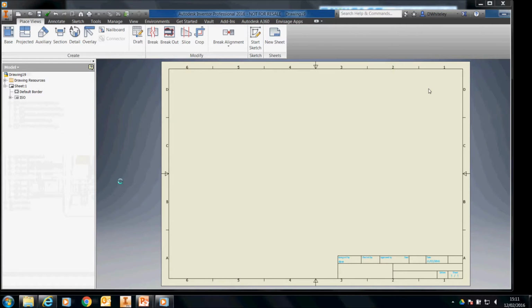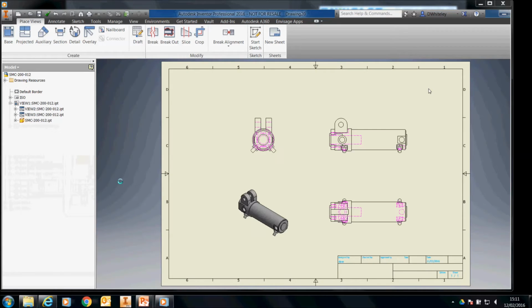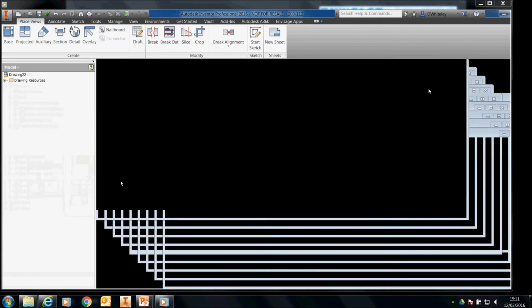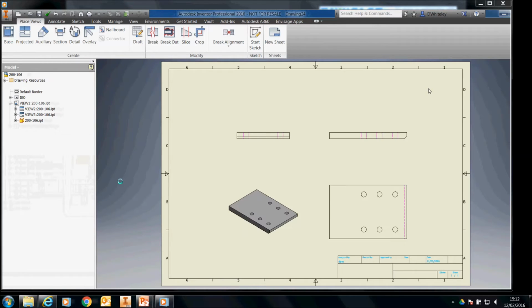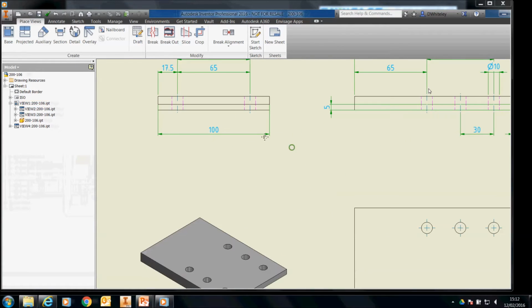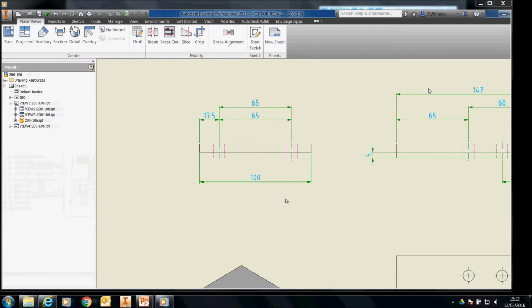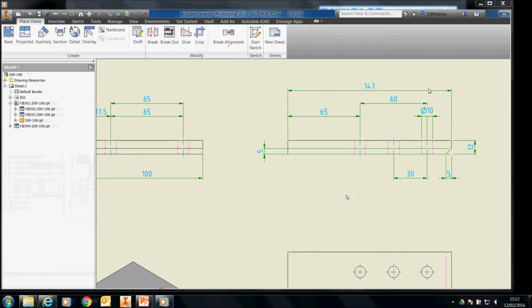And if you've asked it to rotate the base view, it will, to keep the base view horizontal in relationship to your drawing template. The drawings are all left open for you to go ahead and process the drawings in any way you wish, and then obviously save them to whatever folder you require. As you can see in this instance, center lines have been added, and the dimensions have been added, centered and arranged correctly around the views.